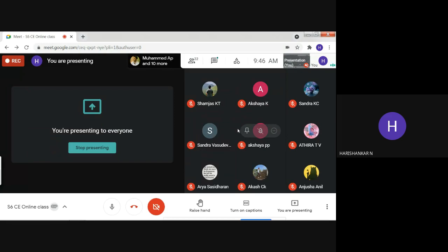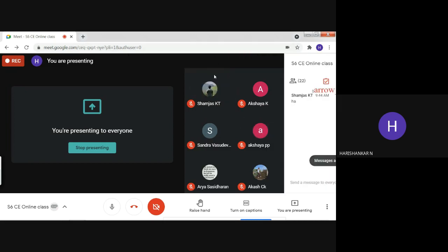So you can calculate the values and you can check it. If they have indirectly given the CBR values, then you have to find it out. Or sometimes they may have given two CBR values: the CBR value of the dense soil foundation, and the CBR value of the bore soil. At that time you have to find out the effective CBR from the graph. That clause 5.2 you can refer. And now let's discuss. Now I hope you can solve the problem. Has anyone solved it or got the answer?